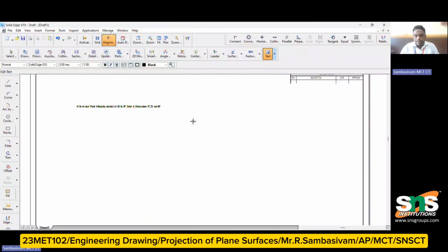So here is the question: a thin circular plate of 48 mm diameter is inclined to the VP, with its plane vertical and inclined at 40 degrees to the VP. The center is 35 mm above HP and 25 mm in front of VP. We have to locate the traces and see how it has to be drawn. This is what we are going to discuss in this video.